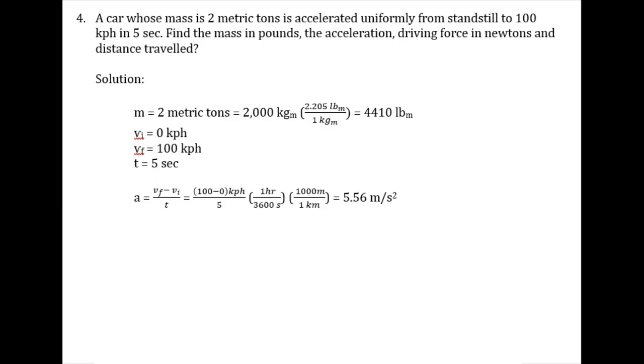To solve driving force, we need to solve first the acceleration, using the formula that acceleration is equal to the quotient of the difference of final and initial velocity and time. Substituting the known value and converting it to meter per second squared, thus we have 5.56 of acceleration. By using force gravity formula, we can solve the driving force, thus we have 11,120 Newton.